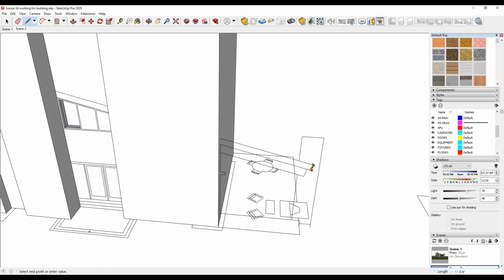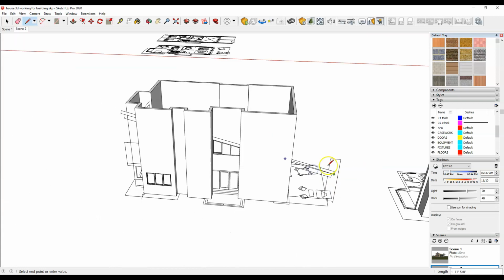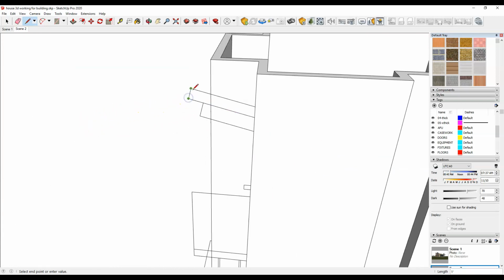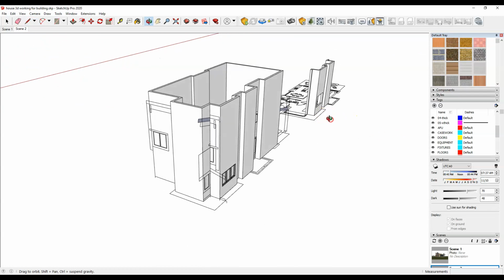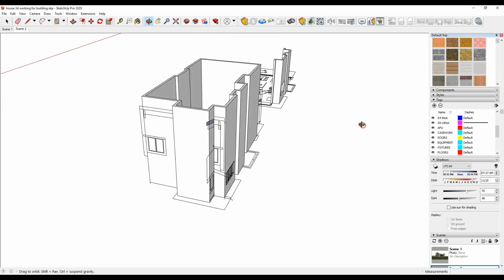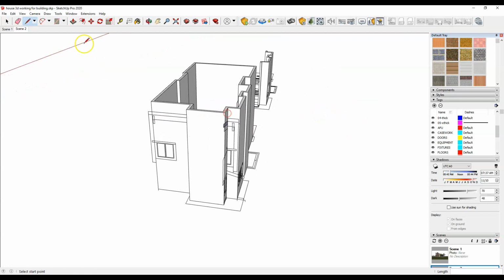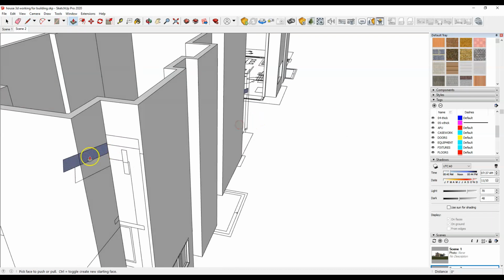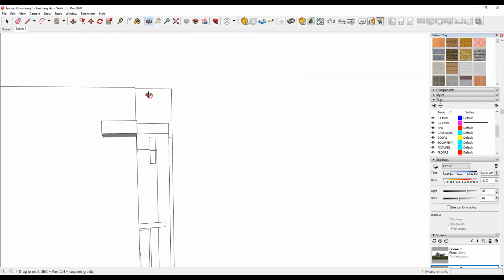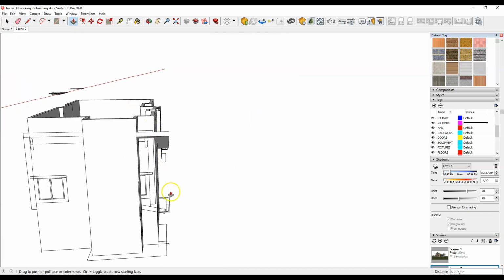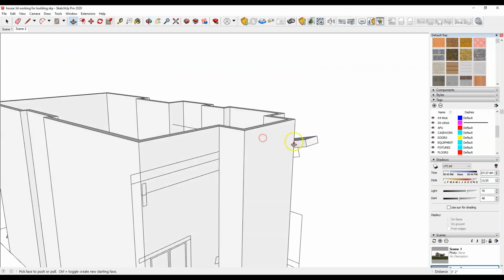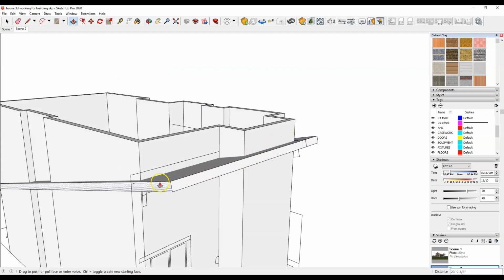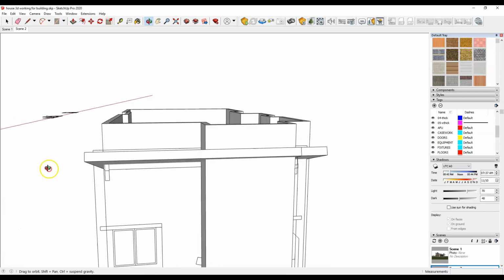I'm going to draw it out here to here, here, there. So I just drew it in elevation. I'm going to push pull it to its right location, forwards and backwards here. So I'm going to come out. I can use this elevation if I have it set in the right spot. Let's see, where is it? It's actually, this roof comes to here. This is tricky. This is part of the trick on this house. I can push pull it all the way this way. You can see I'm just using the elevation to pull it out.